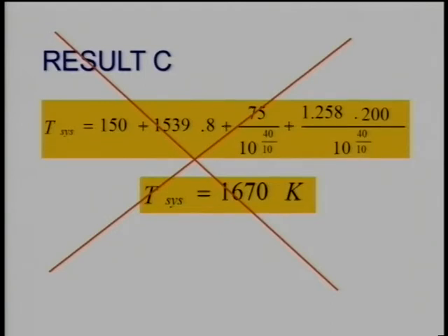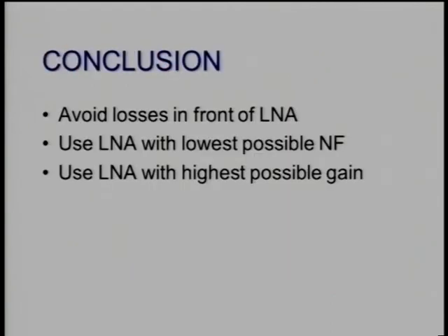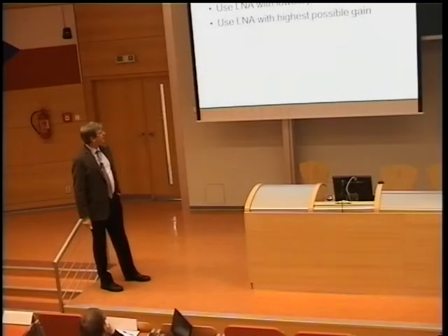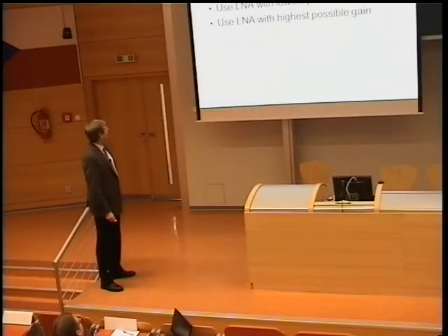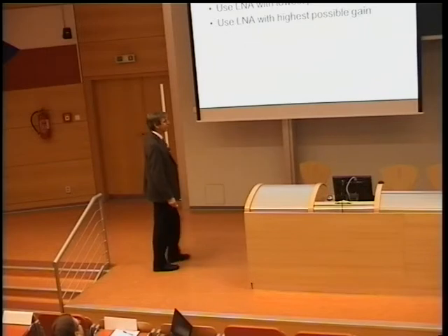So this is no good. The conclusion here is avoid losses up front of the low noise amplifier. Second, use an LNA with the lowest possible noise figure, and use a low noise amplifier with the highest possible gain.